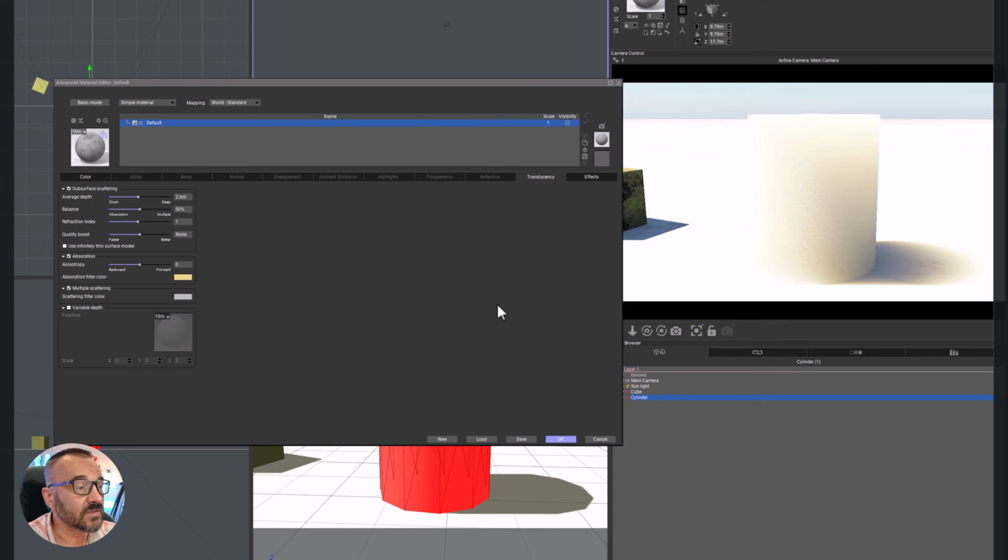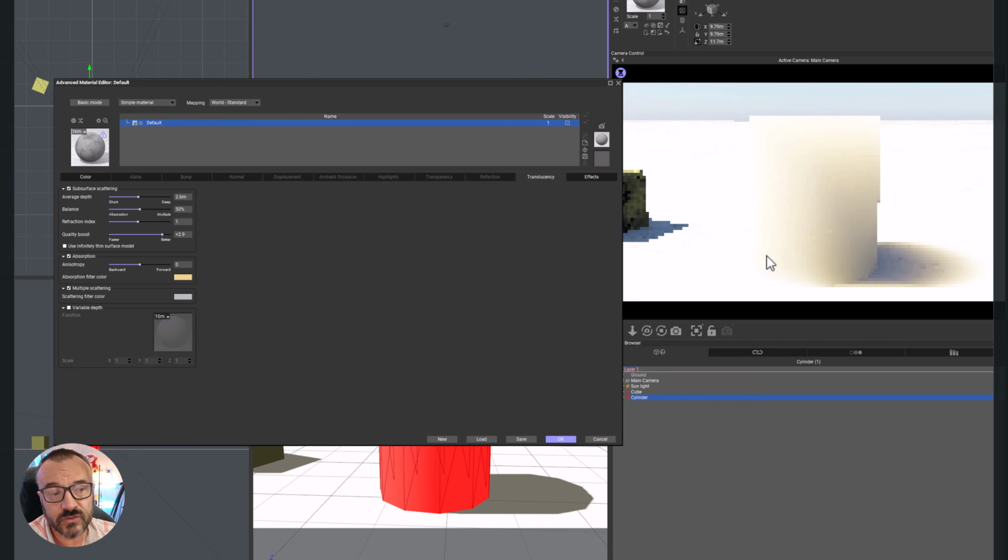To fix this, first, you can always increase the quality of the boost. And you can see as we're increasing, even here it becomes much smoother with better colors. Not perfect, but better. It comes with a price of render time. So you always pay a price with something. You can also go inside the render settings and modify how many times particles can calculate. So you have multiple ways we can do this.